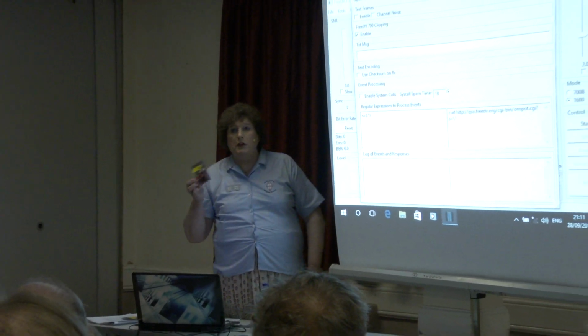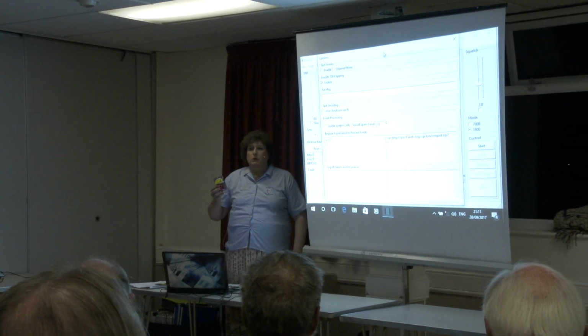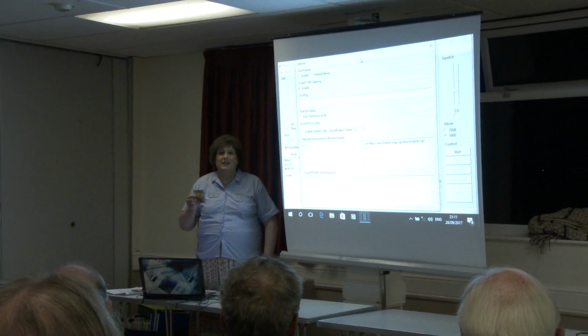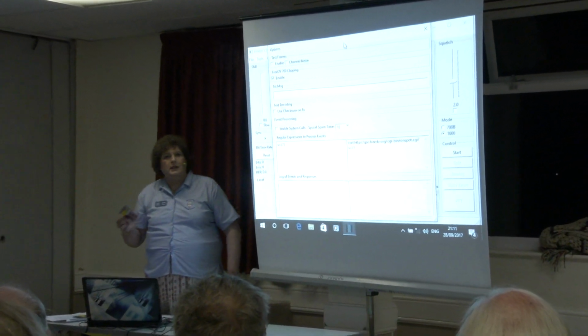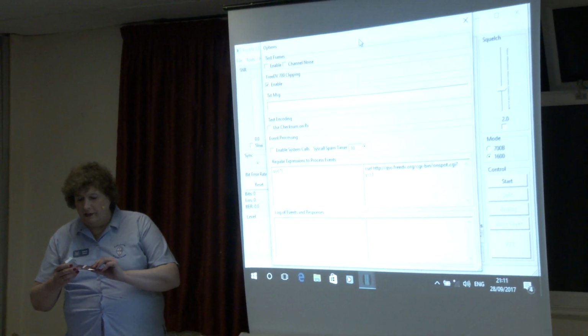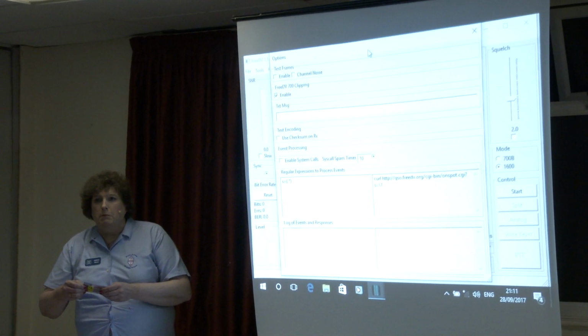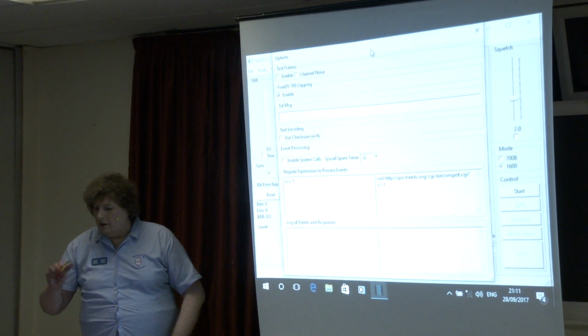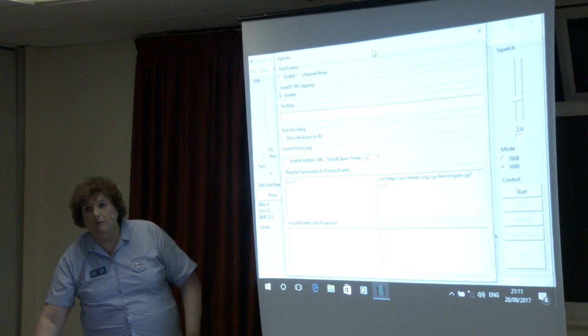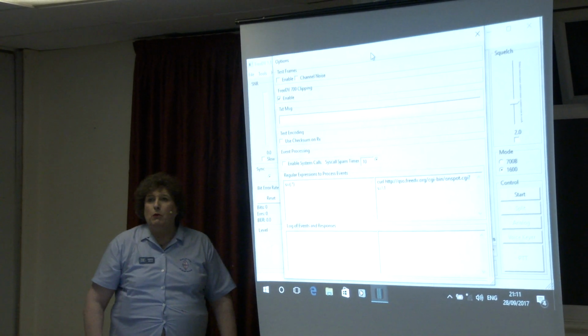Other than that, you would either use the PC version, or you can have a little digital board and install it yourself into some of the older radios that don't take all this modern programming software. You just find a place where you can put a programming lead into it via a 3.5mm jack or something, and basically you can remotely program it accordingly.